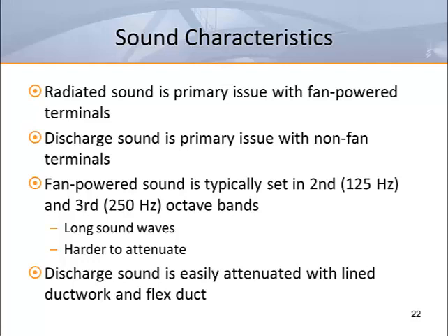Non-fan terminal units have a single noise source called a damper. Properly sized dampers rarely present a noise issue in installations where ductwork is internally lined. In the interest of improved indoor air quality, many buildings are now being designed without exposed lining materials inside the ductwork. When that's the case, extra care must be taken when sizing and selecting products to prevent discharge noise problems.